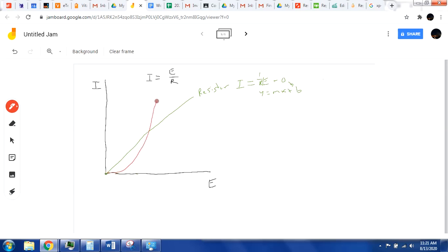However, there are some nonlinear components like an LED. And they look more like this. I should put an X out here somewhere where the resistor catches on fire, but whatever. LEDs, it's a little bit more of a concern. And the reason is, first off, we stay pretty close to 0 for a really long time until we reach some knee voltage or a turn-on voltage.